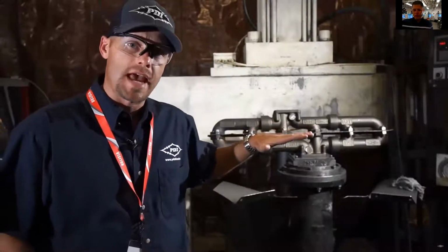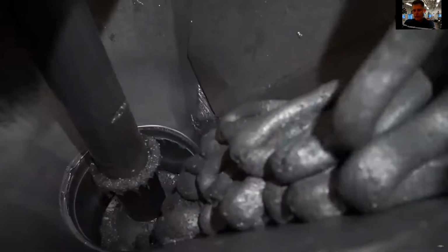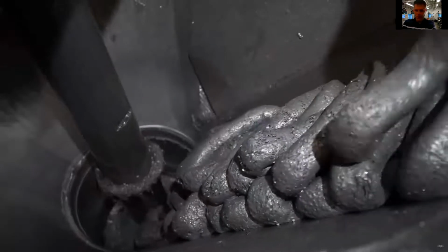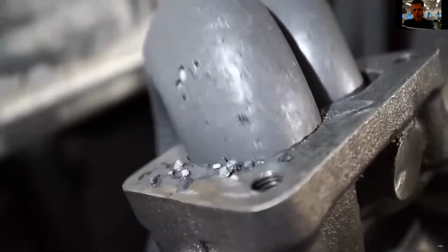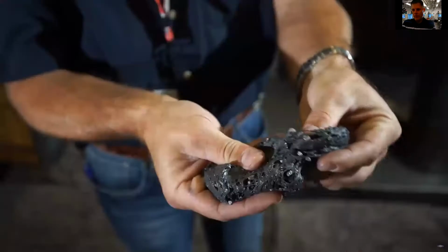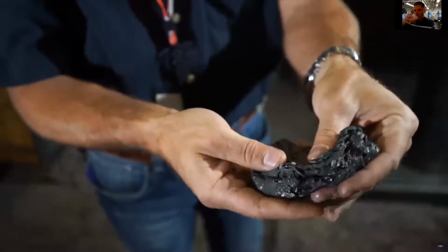The machine behind us is actually underground about 12 feet where it holds the media material, and the large hydraulic cylinder forces the material through the plumbing and flows through the insides of the exhaust manifolds. The media is a putty-like substance with silicon carbide. The silicon carbide is what gives it the abrasive. As it flows through the insides of the manifolds, it is smoothing out all porosity and giving them the absolute best smooth finish.